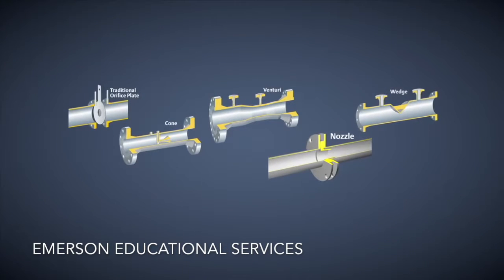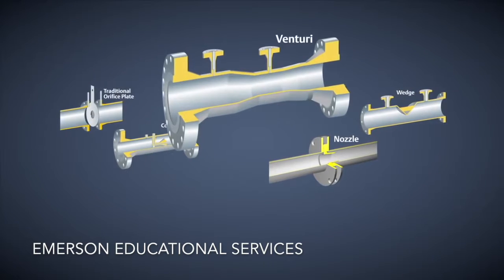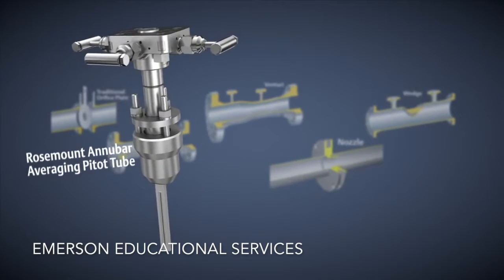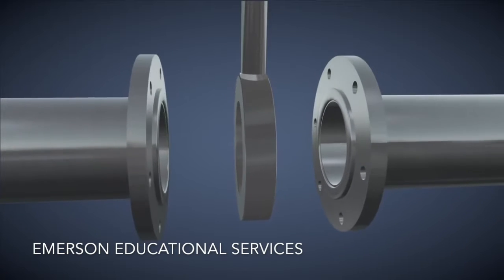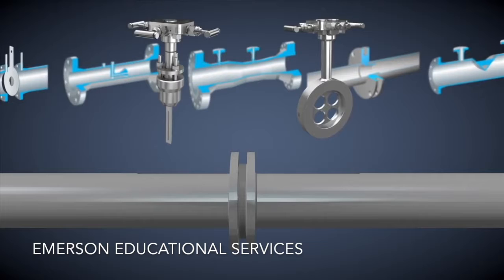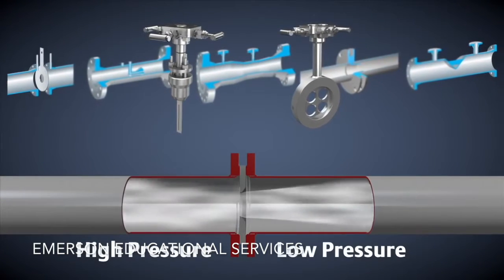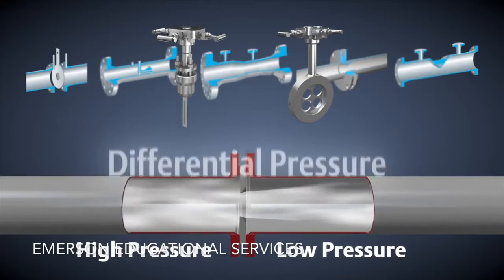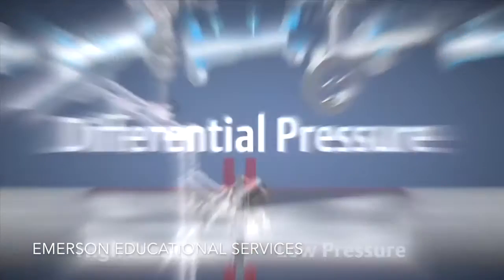There are many types of primary elements, including traditional orifice plate, cone, venturi, nozzle, wedge, Rosemount Annubar averaging pitot tube, and Rosemount conditioning orifice plate. Primary element selection is dependent on process conditions. All of these different primary elements have one thing in common. They constrict the flow in a pipe, causing a pressure drop from one side to the other. The difference in pressures is the differential pressure. The square root of dP is proportional to the flow rate.